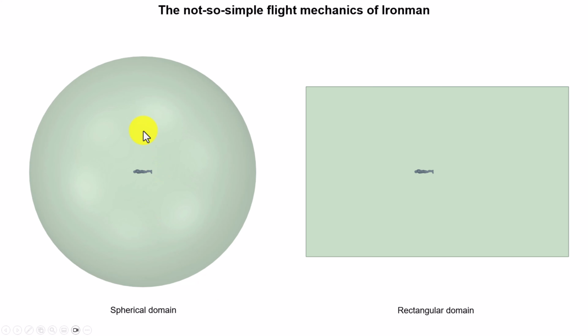So this one I rotate the whole stuff, and it's very simple. Instead in here, if I want to change things, it's a little bit tricky. I will need to remesh or probably divide the boundaries. So this one I would use just for overset meshes for the dynamic part. So there will be another mesh around Ironman here. That being said, all the results that I'm going to show are related to this domain.